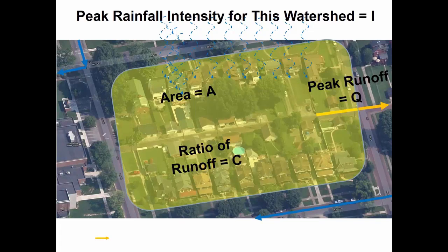And the outlet is just the point that all of the water seems to be draining to. And so if all of the water was going to this point in the watershed, we'd look at, where's the furthest journey that water is taking. Maybe the water has to flow along this sidewalk, get into the alley, and then flow down the alley till it finally gets to there. And so we'd find that distance and estimate the time that it takes.